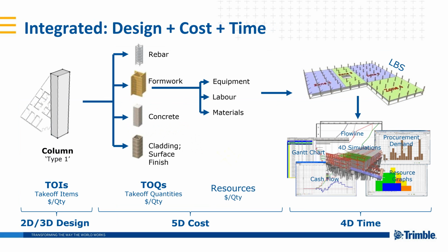And then we can also figure out something like the cladding. From each one of those subcomponents, we can further derive things like the labor, equipment, and material. So if we know that there's 100 square feet of formwork, we have a basic understanding of how much labor it takes to put that in. We have a basic understanding of how much waste we'd want to apply to that formwork and how much material we'd need, and also what kind of equipment would be needed to get that job done.